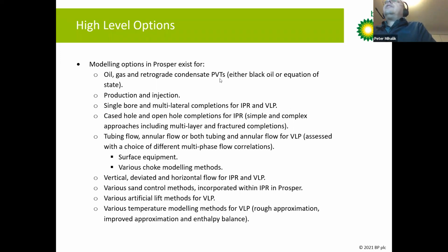And you can do some very interesting analyses with that. Even if you're just modeling a single wellbore, you get some results from that model that you can't get from any of the other models. We can model cased hole or open hole completions, which could be very simple in approach or more complex, including multiple layers and fractured completions. We can model different flow conduits: tubing flow, annular flow, or both tubing and annular flow.